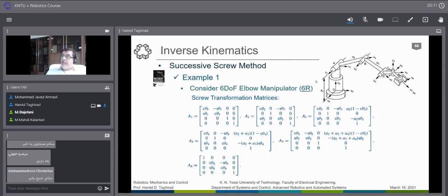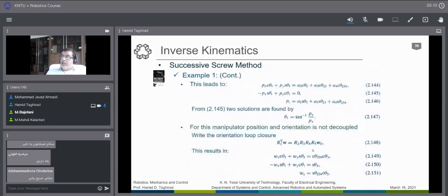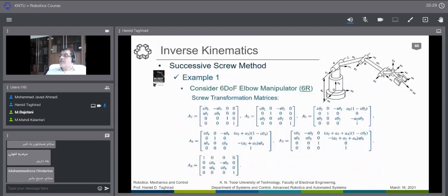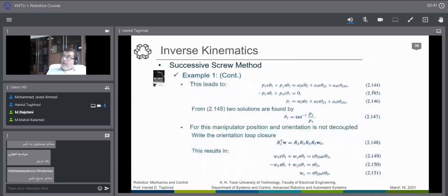When we have W0, we can find that quite easily, but the W is a general orientation of the manipulator, which has WX, WY, WZ, the three given components. We use now the W1, and as you see here, we need all the screw coordinates 1 to 5, not the sixth one. The sixth one is around the W. So we use the W to just remove the sixth one and use all 5 rotation matrices.